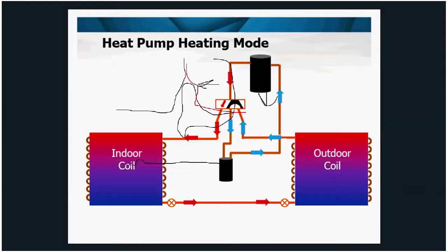Now, when this switch occurs, we've got hot gas going into one coil, we switch positions, it goes into the other coil, and as this refrigerant is radically changing direction, there's a chance that liquid refrigerant from one of the coils will dump back into the accumulator, and that's what it's for. It's a place for that liquid refrigerant to go to evaporate before it goes back to the compressor.